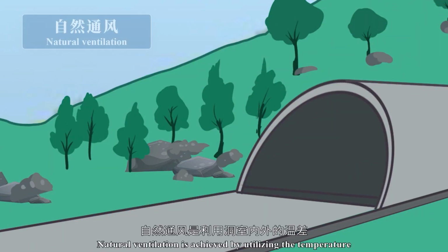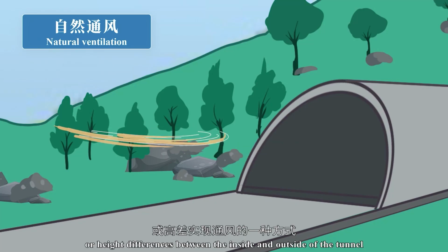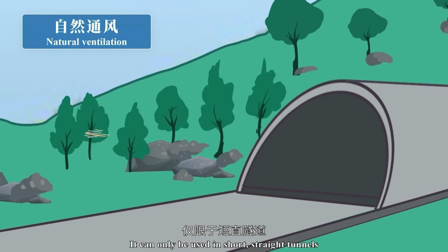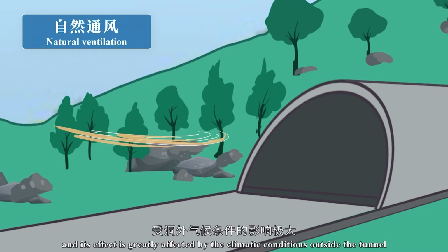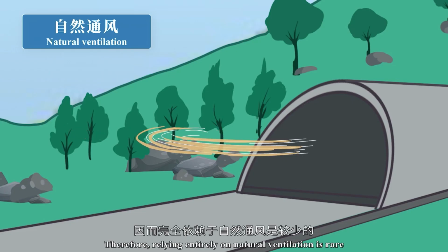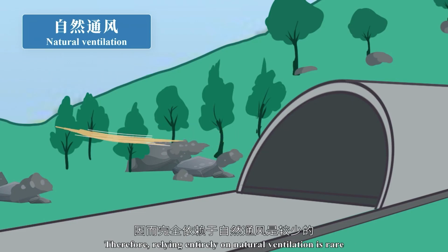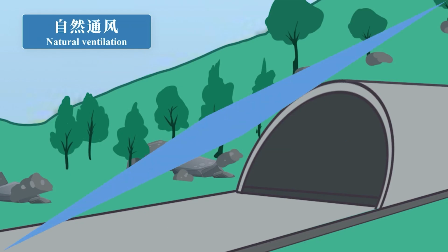Natural ventilation is achieved by utilizing the temperature or height differences between the inside and outside of the tunnel. It can only be used in short, straight tunnels, and its effect is greatly affected by the climatic conditions outside the tunnel. Therefore, relying entirely on natural ventilation is rare, and most tunnels adopt mechanical ventilation.